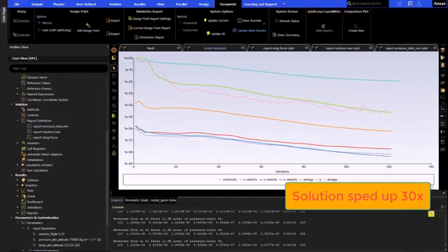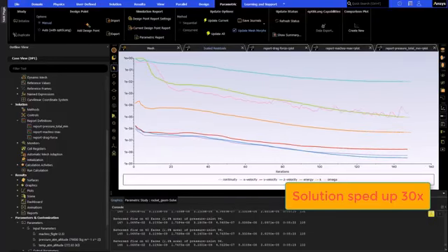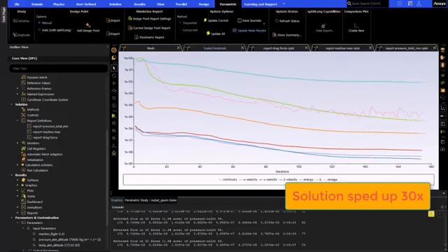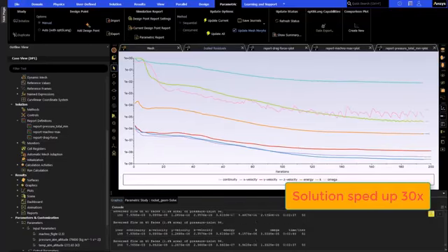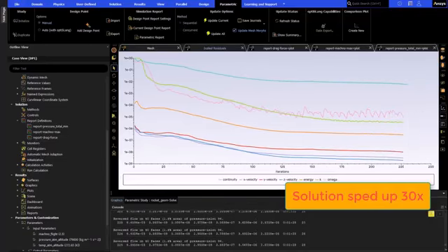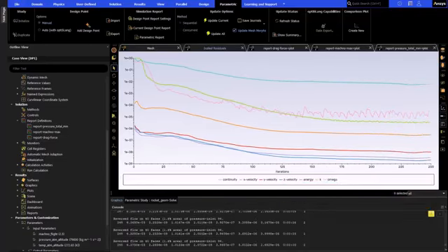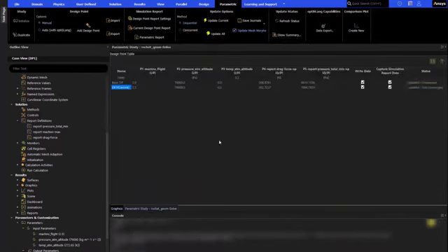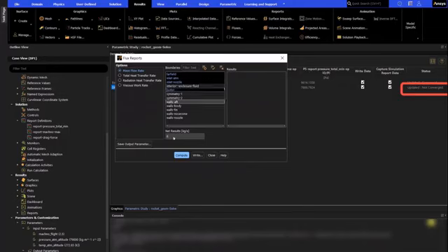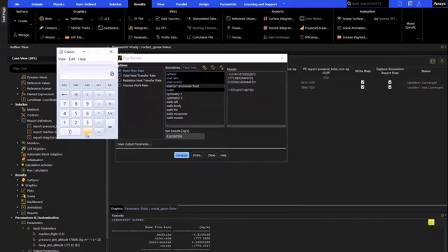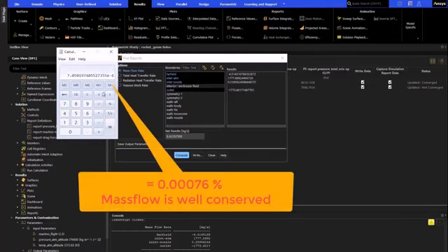For this design point, residual limits are not met, and the residual's progress flatlines. You could pause the simulation and adjust the solver settings. However, instead, we'll let the run complete and check the monitors. Even though residual convergence was not met, mass flow in and out of the domain is computed, and we find that the mass flow is conserved. The monitors are also invariant, so the results are valid.